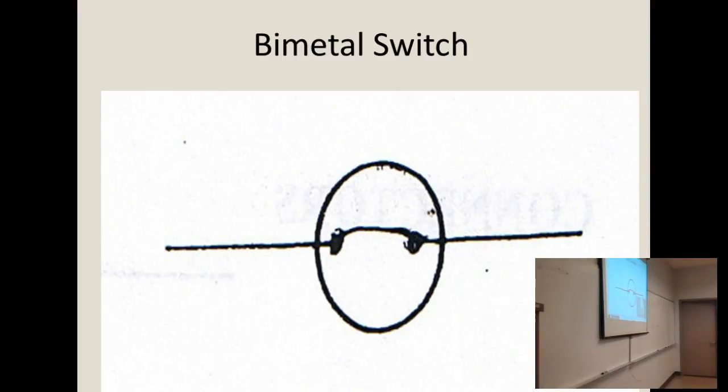And when it warps open, the electricity can't pass through it. This one says L175-40F. That means at around 175, it's going to open. When it cools down 40 degrees below that, approximately, it's going to close. Okay.